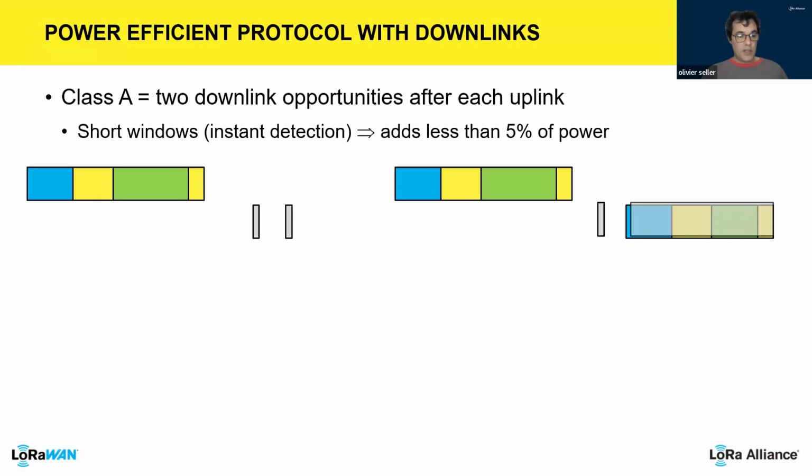And here, this uplink is sent. The device opens 2 reception windows, but there is no signal. So between the transmission and the windows, and after the windows, the device is in sleep mode where the power consumption is very low. Only there is the device active, and there active in reception. Then comes the next transmit frame. The first reception window is open but yields no detection.